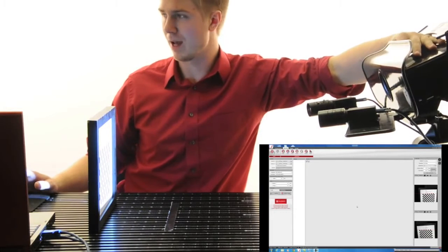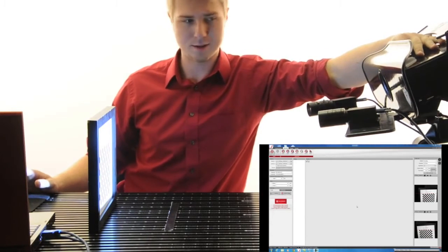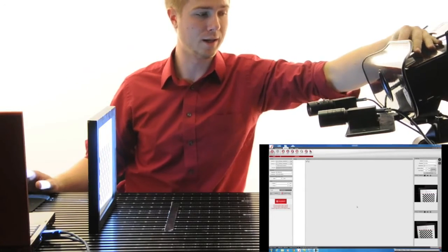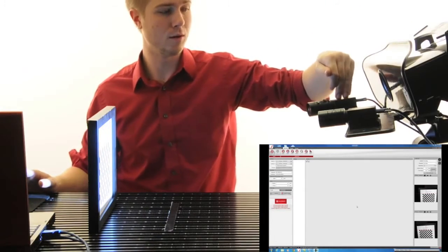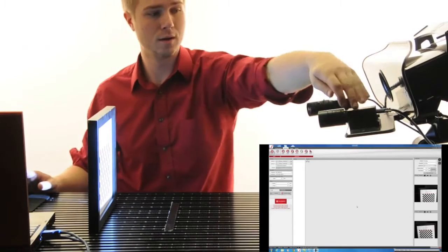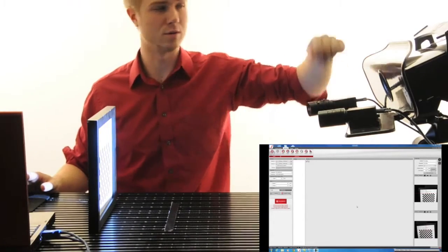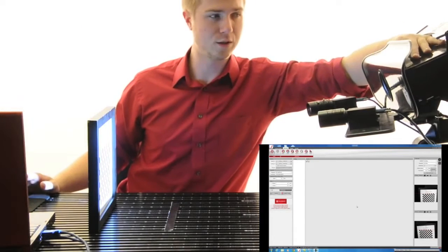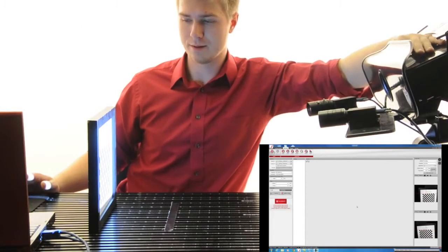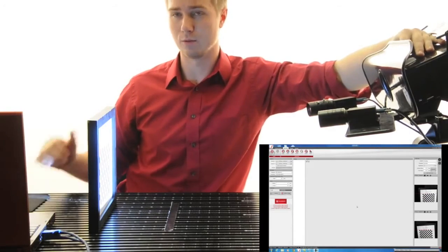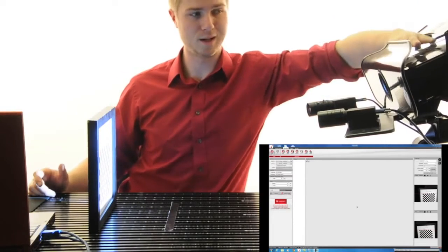When you're using a larger scanner setup, so if you're using anything that's on the medium or the large bolt hole locations on the bridge, we'll want to turn this zoom ring all the way to the right, so all the way towards me.